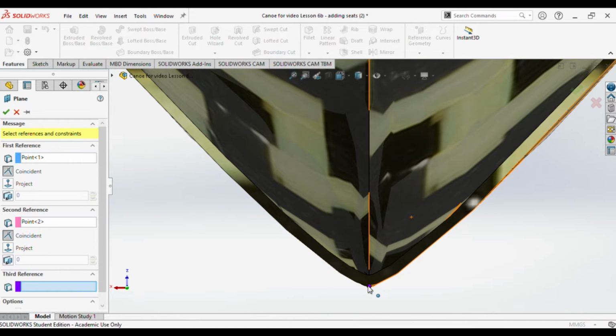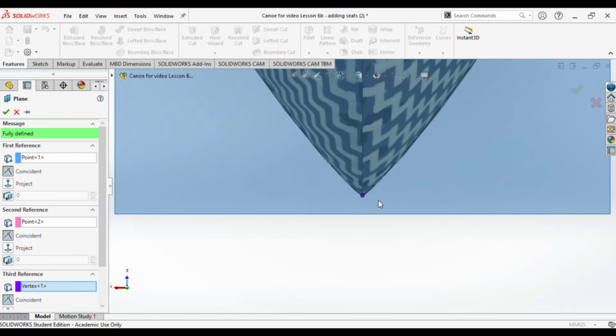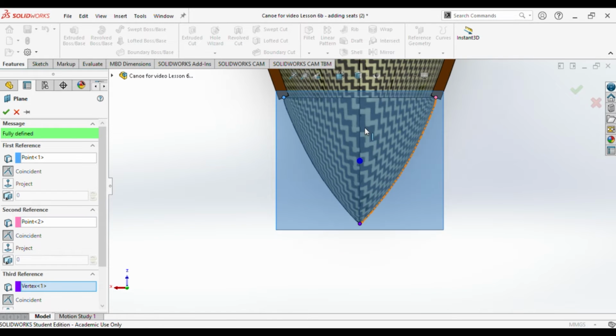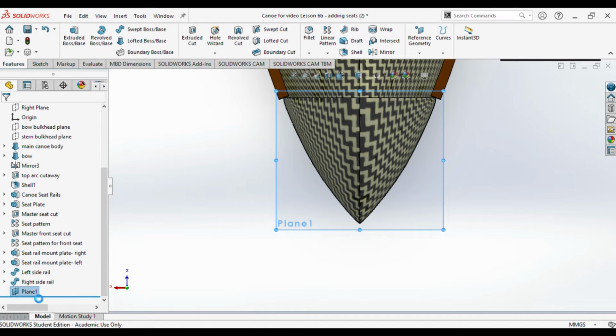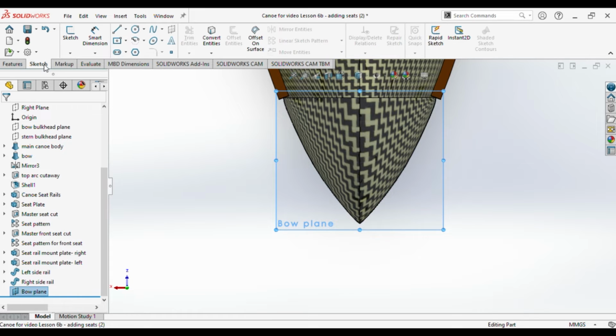So, we're going to use a standard extrusion to draw this part, but first we'll need to create a plane to draw it on. We'll create that plane by selecting 3 points. If we use the node at the ends of the main shell and then the very tip of the end shell, we'll get a plane that runs very close to the surface at the top of the portion of the shell we still need to cap. We'll draw a profile for our bow on this plane. Then we'll cut a hole for a grab handle, and we'll put fillets on it to make it comfortable to use.